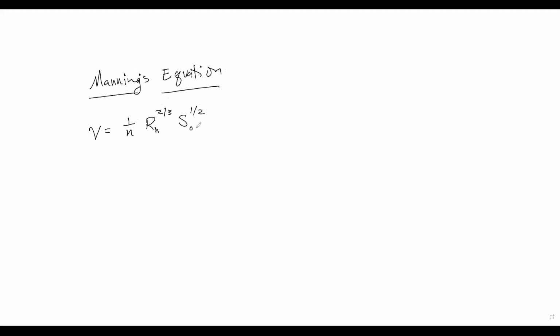And this slope, well, you're going to go back and forth on this. If you use this equation in your career, we just did uniform flow where S naught is equal to SE under uniform flow conditions. But really, in what we did in pipe flow, this really should be SE. So we often substitute in S naught because we assume uniform flow in some situations. But ultimately we need to be putting the energy slope in there, or the slope of the energy grade line. So just keep that in mind, because under gradually varied flow conditions, we're going to be using this term.